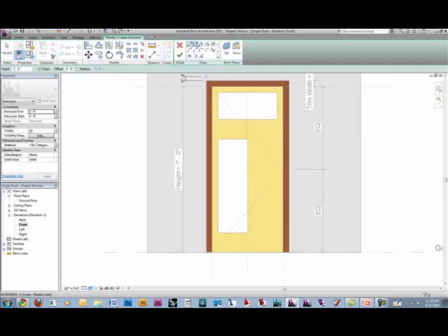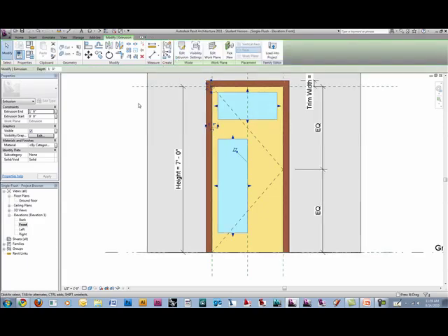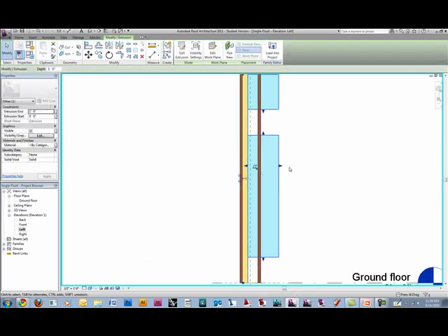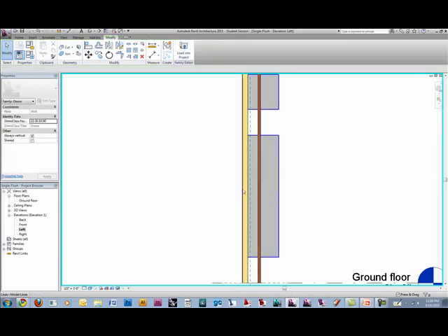Ta-da! And we're going to draw rectangles inside of these rectangles. And look, we're going to tell it to lock because the void's already cut the space, so we lock it to that voided space. And because that voided space has all the offsets tied to it, this form is also going to have those offsets by default. That's kind of nice. So let's go back to left, and I'm going to hide the trim because it's a little in my way.